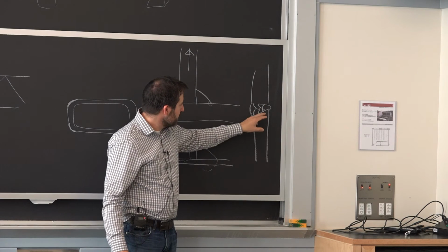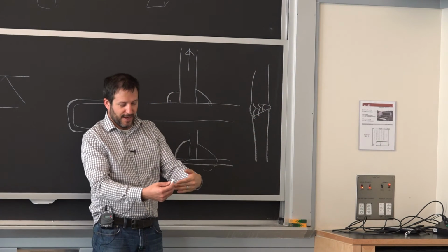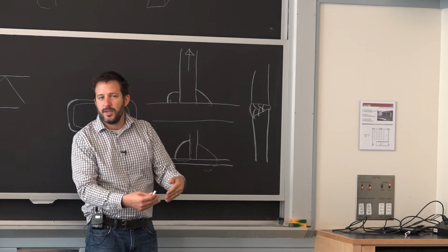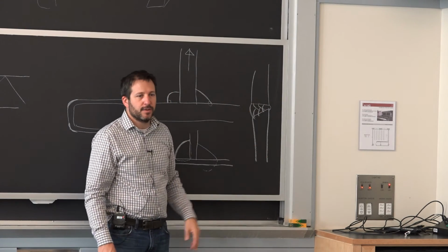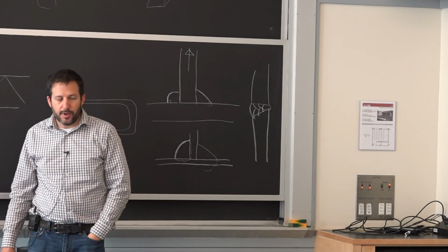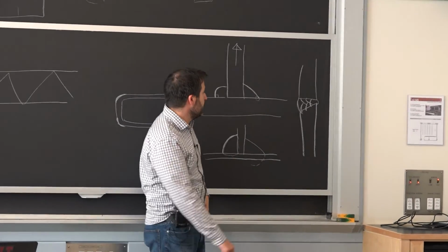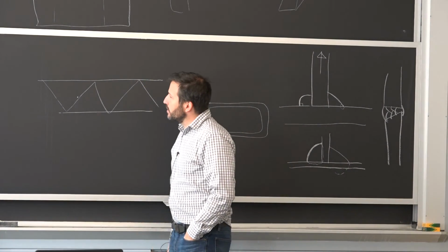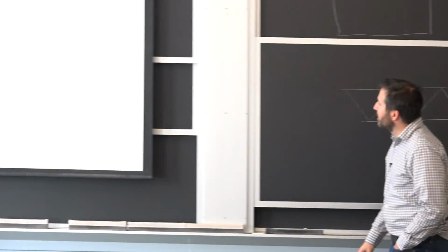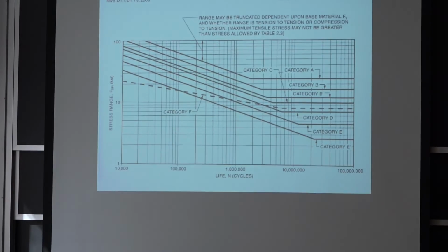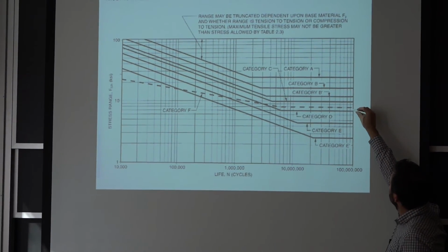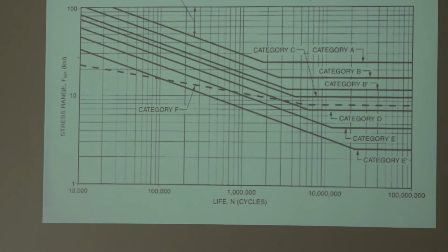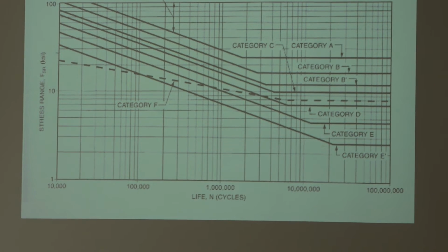And the residual stresses in this situation, you get an actual deflection of the part because they're not connected otherwise. So you'll have a bigger allowable. And also, if you can weld from both sides here, that gives you an extra category. So let's say we look at a category C. That is when you have all that reinforcement. So somewhere in here, above about 10 KSI.